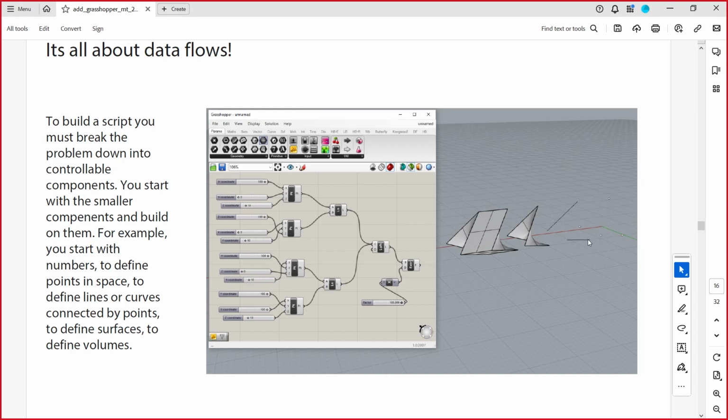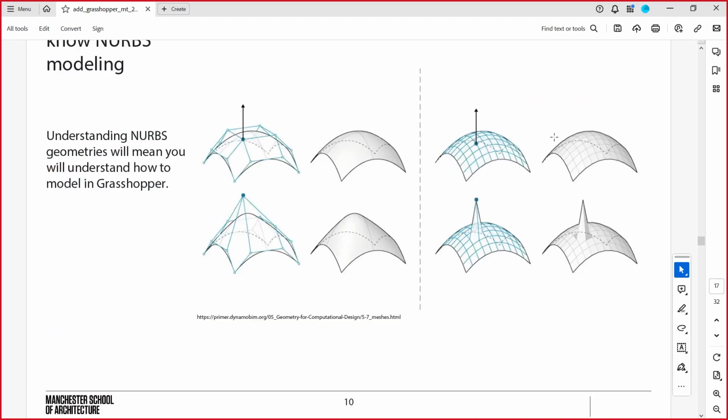Okay. You can see here I have an example on the slide. So we start off with 4 points. We create 2 lines, we create a surface between the lines, and then by extruding the surface, we get a volume. Right? So it's very methodical, very logical, and everything follows. Right? So if I go back, change anything from the beginning, everything gets re-executed. Okay. Yeah? In this case, is it trimmed surface or not? This one's untrimmed. And extrusion is untrimmed. Loft is untrimmed, and extrusion is untrimmed. So we'll get into that later.